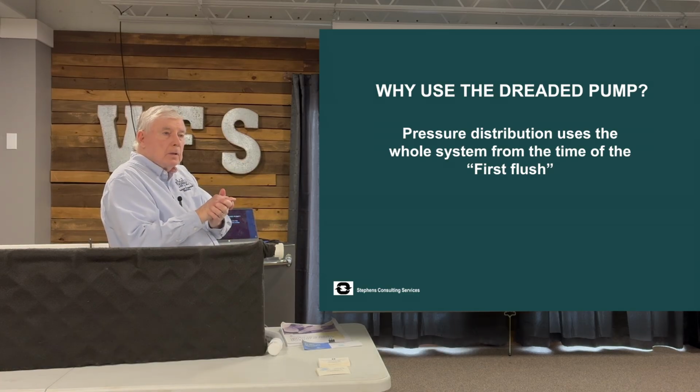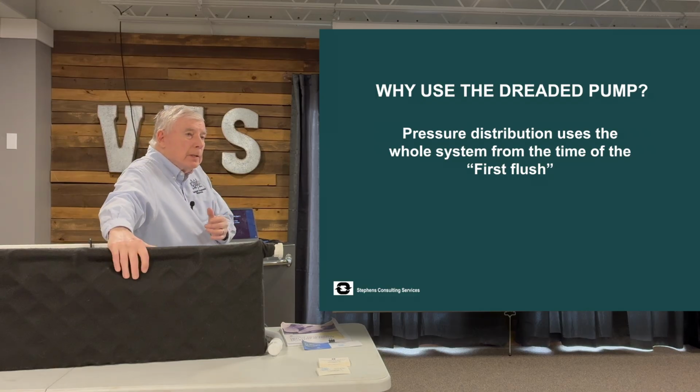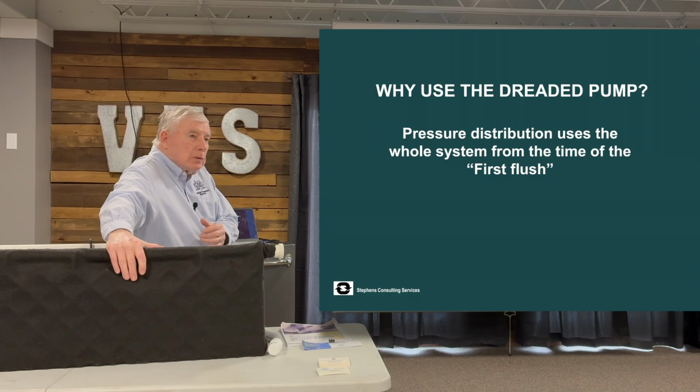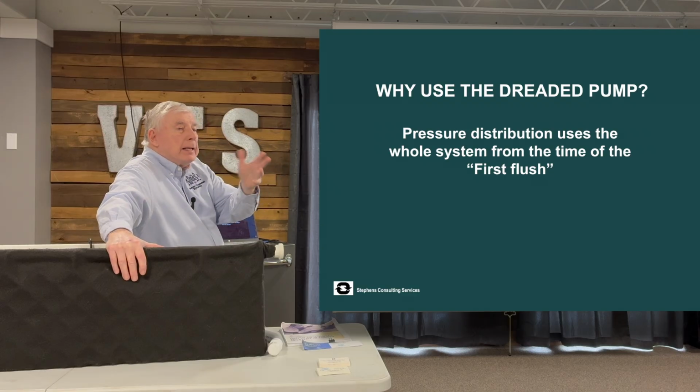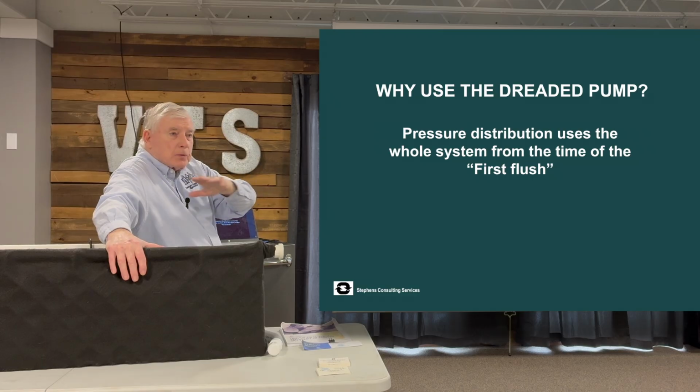How long does the pump normally run per day? Like, we talk about pressure distribution, I'm completely new to the industry. Well, does it run for 10 minutes, an hour, or 10 hours a day? Or... How about a minute at a time? Okay, so let's say you've got a 50-gallon a minute pump feeding a system. And the flow from that house, I could prove it to you, but on the average it's going to be 150 gallons per day per household or less. That's the actual flow.